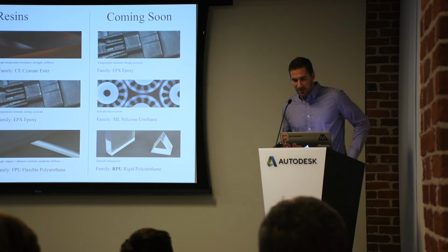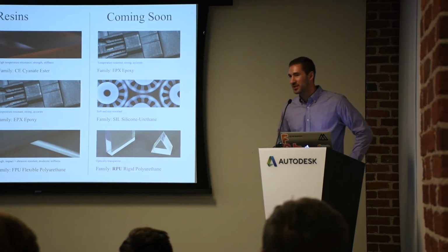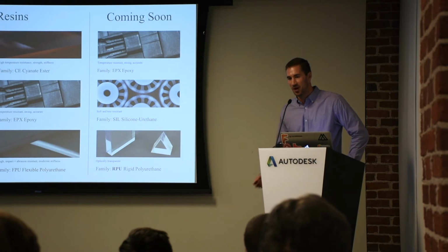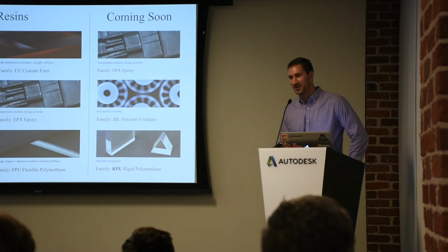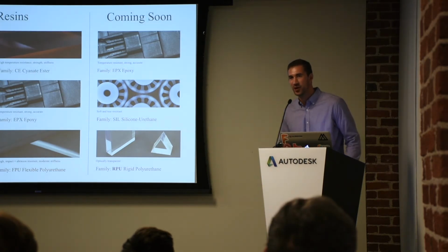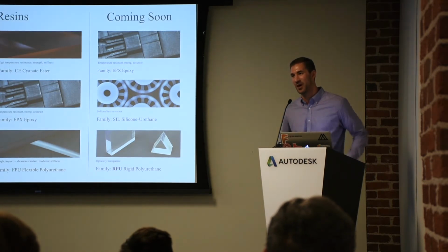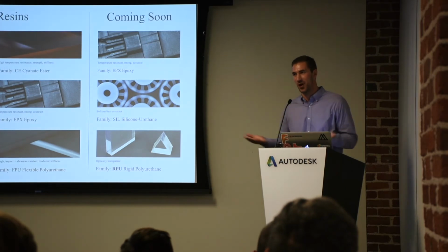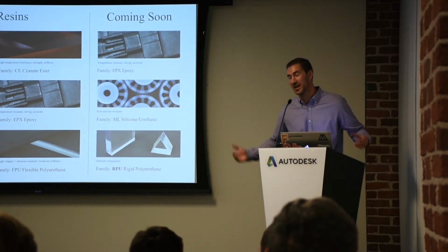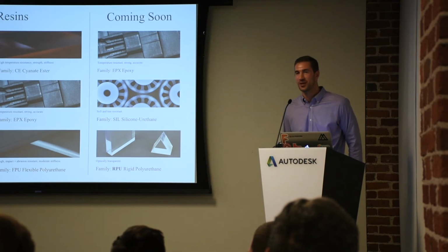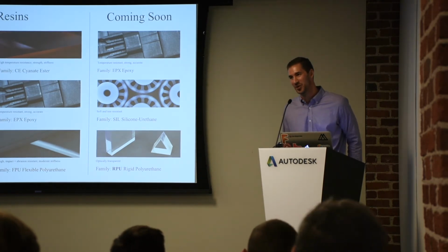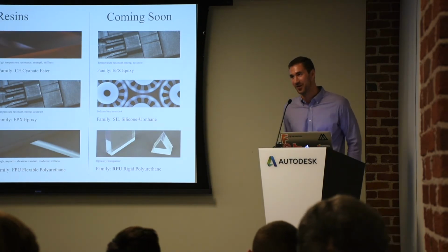We have a material, cyanate ester, that you can see up there, which is probably just about the highest temperature polymer that you can print today. It's about a 230 degrees C heat deflection temperature. I was having a discussion with a gentleman earlier about this, and it's just very hard to print that material in really thick sections. Our process does not lend itself well to big, thick, blocky things that look like they were designed to be machined. If we think back to that flow, that becomes really hard and really slow and actually generates a lot of heat. So the short answer is yes, we can do it with small molding tools, but it doesn't scale very well.